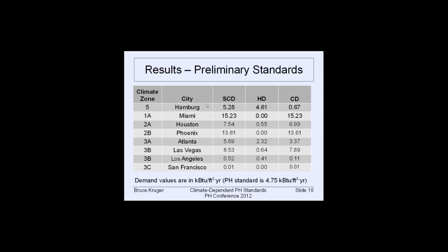I just want to say a couple of things. First of all, you haven't said what the heating is, and your optimization graph is in terms of source energy, and this is demand. And I think source is absolutely right when you focus on it. And when you apply primary energy factors, cooling demand is lower than consumption because of CO2, and heating, if fossil, is higher, then we really have to take this one more step and look at the true power energy impact.